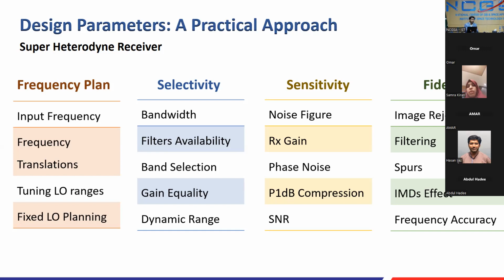Who defines the accuracy? The accuracy is defined by the PLLs: the fixed frequency LO, the fixed frequency sources, I will share later what type we use, and the tuning local oscillators, the TLOs. Usually in one application we use a DDS, but in one I'm working on, we are using this architecture. It produces a 24 to 40 gigahertz signal.